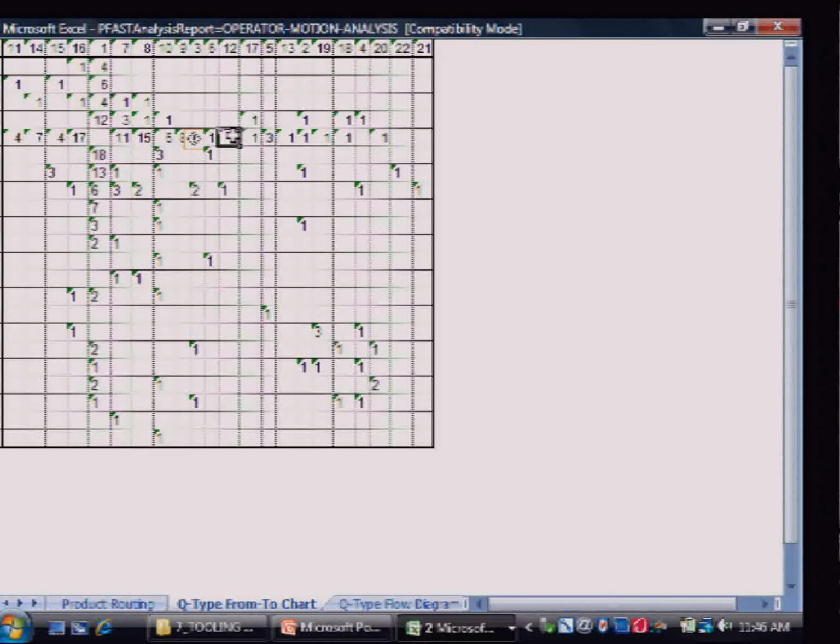All that we're trying to demonstrate here is that in the job shop that is going to make a variety of parts, when you drill down to the individual constraint work centers and you look at things like setup production, part of the setup time improvements will be through layout changes. You can also use FAST to look at different dies or parts and try and create either tooling families or die groups. Again, these are different applications of the same algorithms. Here, all I'm trying to do is focus on the layout of the workplace.